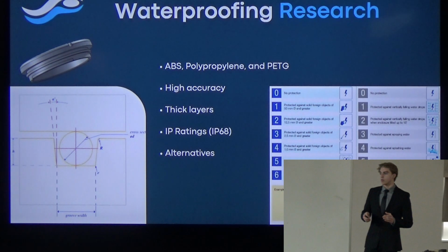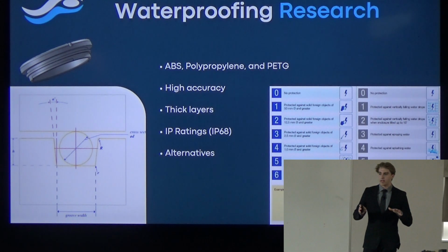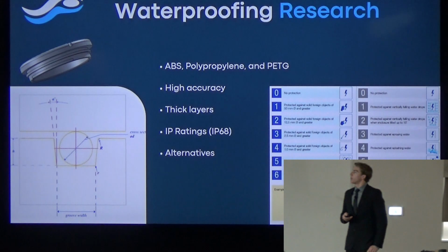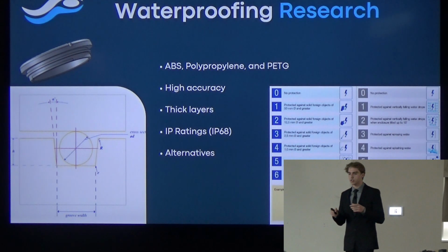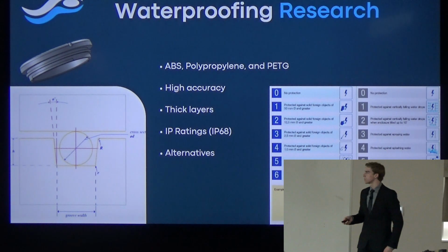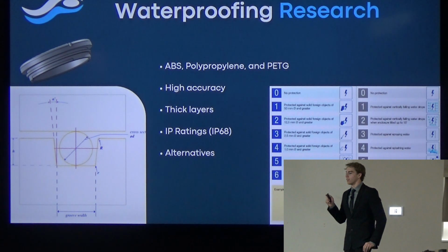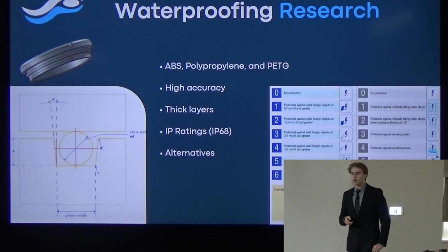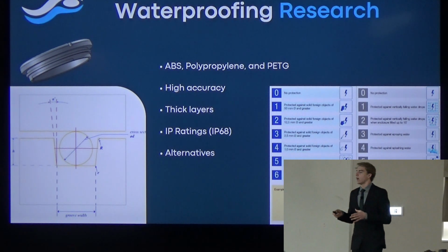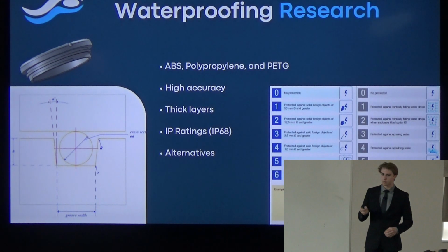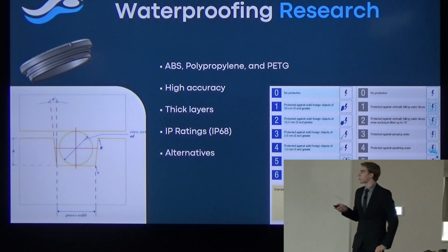However, it had a lot of issues with deforming and kind of bending, depending on weight. And then polypropylene. This is the material used in laundry detergent bottles, so it is definitely water resistant. However, it's very hard to print and not available to us at Grandview. Additionally, the final one I found was PETG, which is a polymer that is actually hydrophobic and holds out water extremely well. It's extremely rigid, so it doesn't have as much risk of deforming and bending while printing.